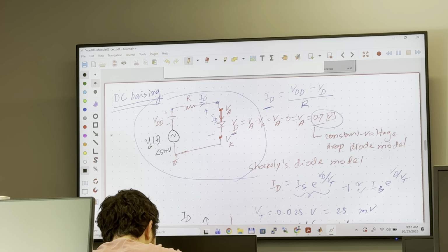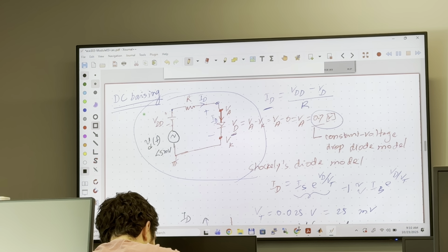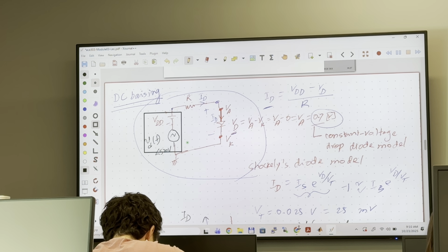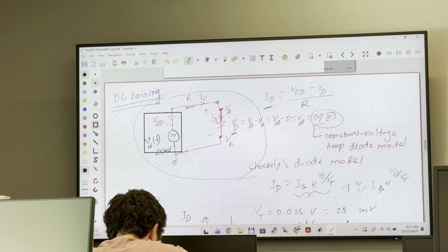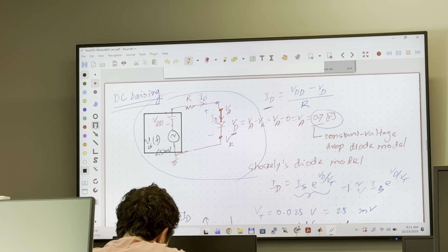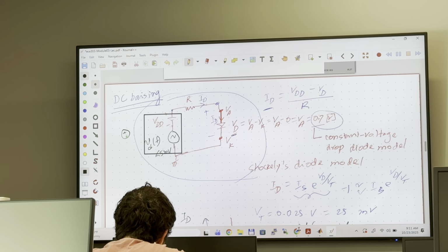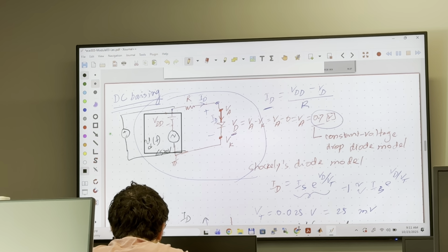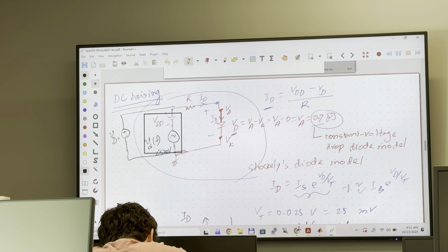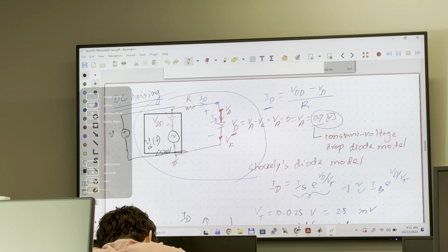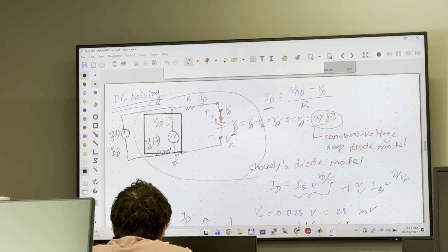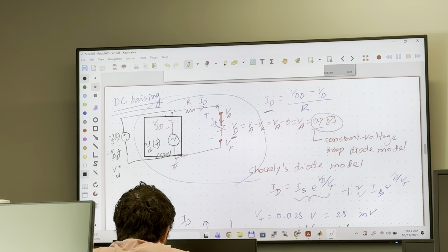And we have this DC voltage. Throughout this course, it is my notation that the total voltage, the total DC plus this AC component, I am going to denote with a lowercase v and an uppercase subscript D. This means that it has DC plus AC. So it is basically VDD plus lowercase vd.